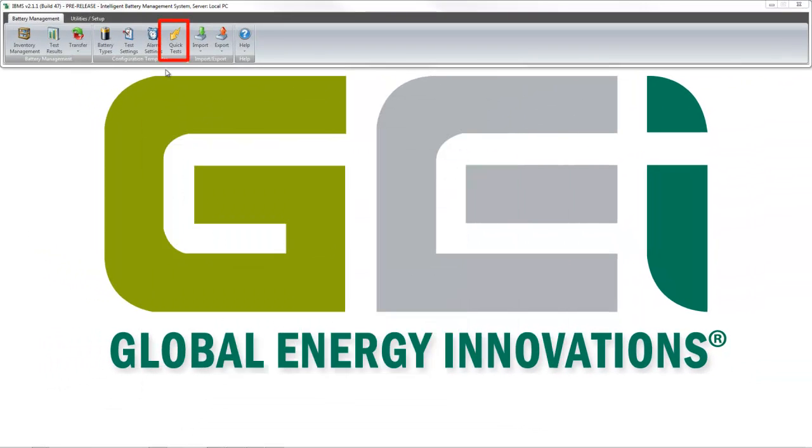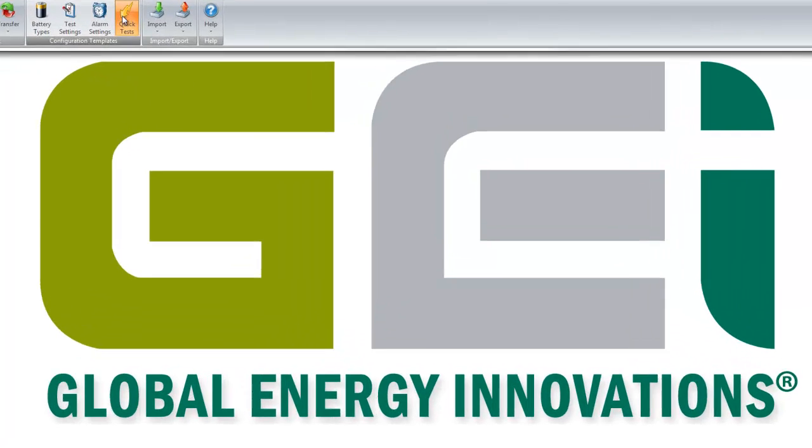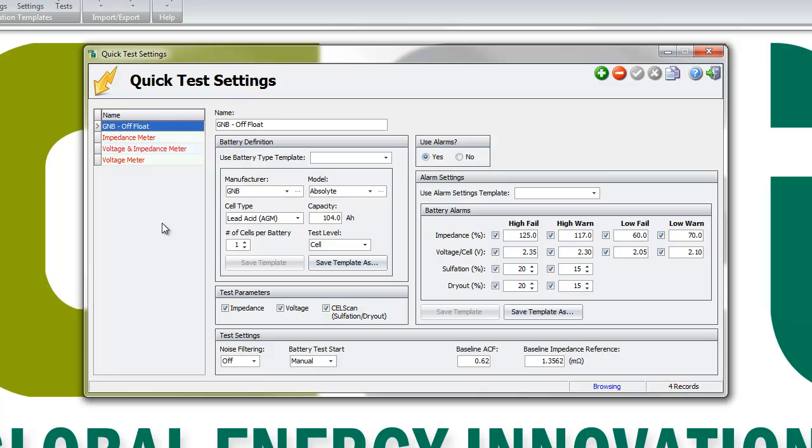Quick test is a different type of template. Quick test templates are not used in string configuration, but to define complex quick test settings to be used in the analyzer. Click on Quick Test to open the Quick Test window. The organization is similar to the other templates. On the left, the default quick tests are listed. You cannot edit or erase those default templates.